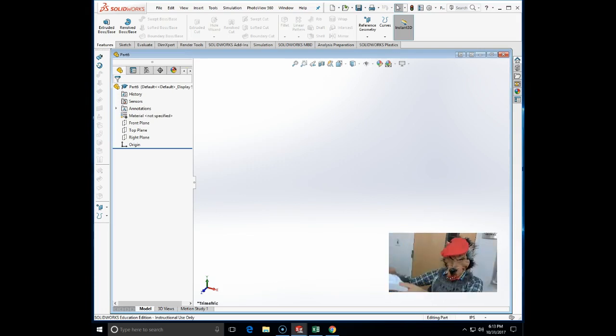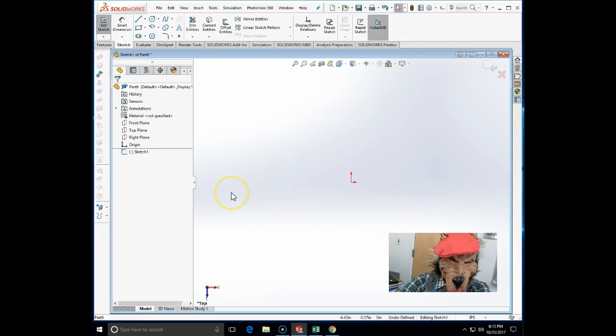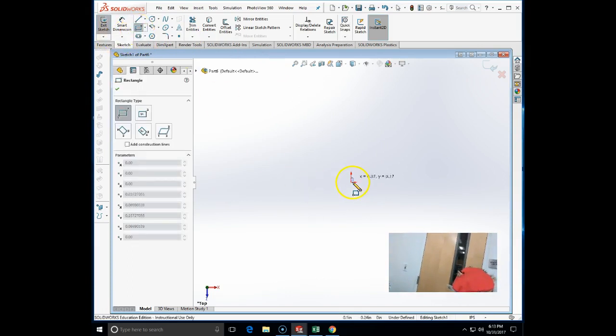On page 642, we need to make a plate with two holes, and then make a pin and an assembly onto which we will bring the gear. The gears are always brought in assembly mode from the toolbox, and they are generated as a toolbox component. So to make this plate, we are going to make a single sketch.